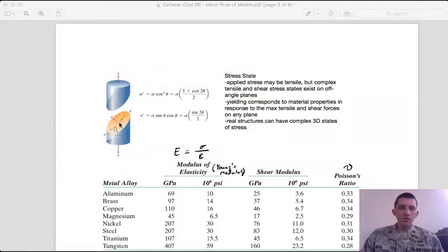Within that state of stress, right, you would have two dimensions along that plane, and you can define them mathematically in terms of the overall stress applied to the ends of the sample, right? Ultimately, that's what we're talking about. And these mathematical relationships reduce to our initial look where we're looking at just the cross-section if we think about the plane with an angle relative to the cross-section of 0, right?